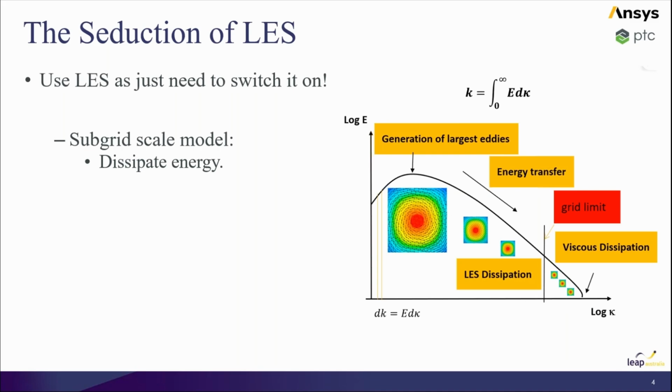And you're down there at what's called the Kolmogorov scale, where the dissipation by viscosity is so fast, we do not have smaller and smaller eddies. They literally disappear. And it's at that region that we've taken all that kinetic energy out. So in order to do modeling here, we have to specify this subgrid scale model to dissipate energy. And that's not such a big task. There's lots of models, but as long as you get rid of the energy there in a meaningful way, that'll work.